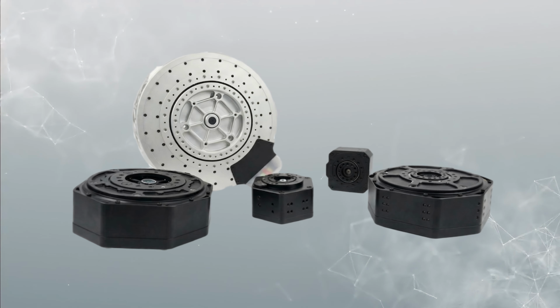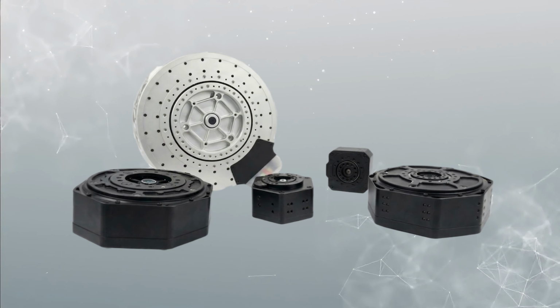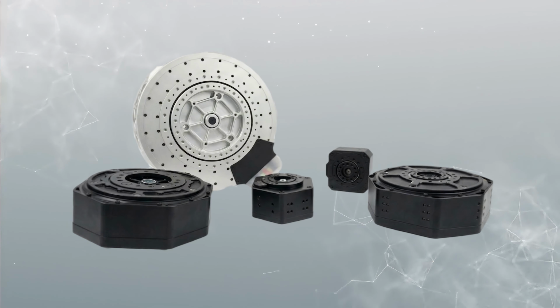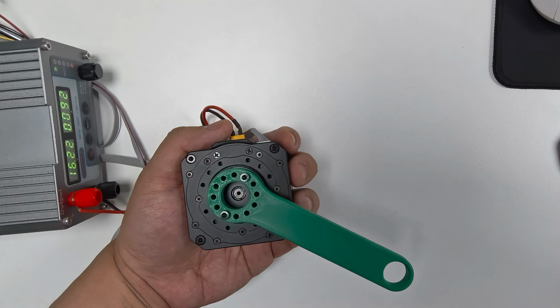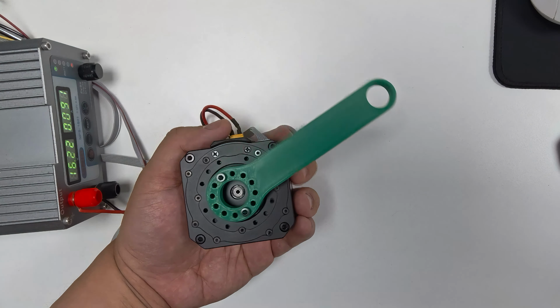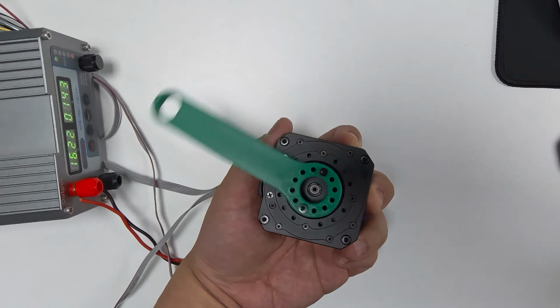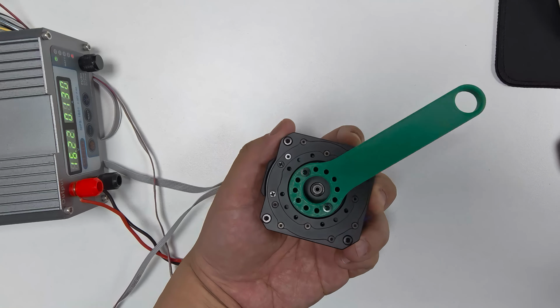Hardware specs are only a fraction of the story if your PID loops are poorly tuned. Mastering PID tuning is essential to unlock the true potential of these proprioceptive actuators. Many developers struggle with actuators feeling too soft in position mode or violently vibrating under load. Usually, the issue isn't a hardware limitation, it's tuning the loops in the wrong order.